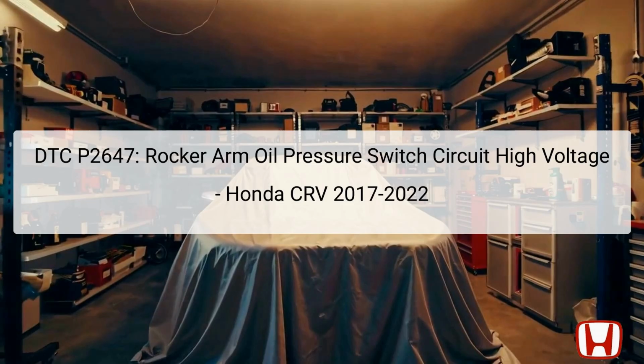The rocker arm oil pressure switch monitors oil pressure and signals the powertrain control module (PCM) to adjust the VTEC system accordingly. Commonly, this switch is located on the cylinder head, making it accessible during engine checks. To effectively troubleshoot this DTC, it is essential to understand the operation of the rocker arm oil pressure switch, how it impacts engine performance, and the implications of a high voltage reading, as it can lead to reduced engine efficiency